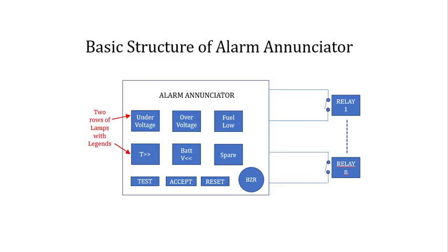For the purpose of monitoring the state of equipment, almost every machine carries a switch that changes state when some specific parameter of the machine goes beyond desired level. Take the case of a machine for which upper and lower limits of supply voltage are specified. In such a machine, there are two relays.